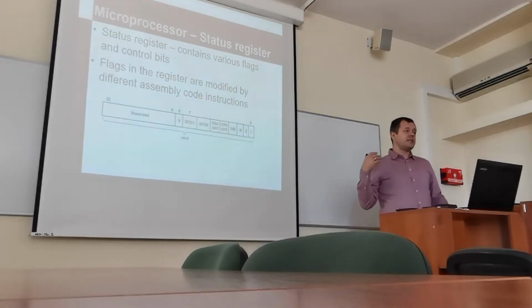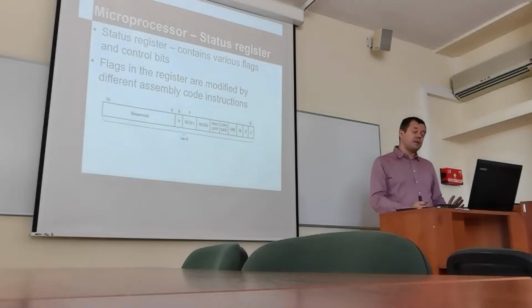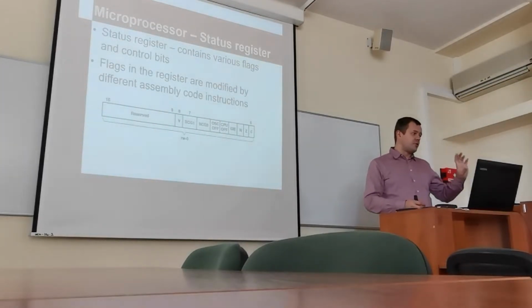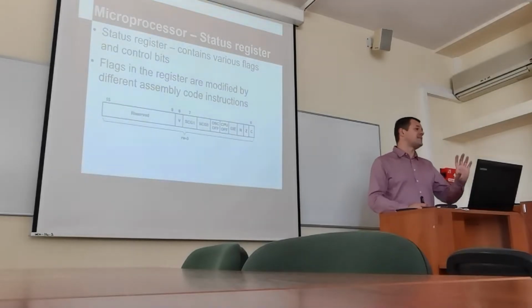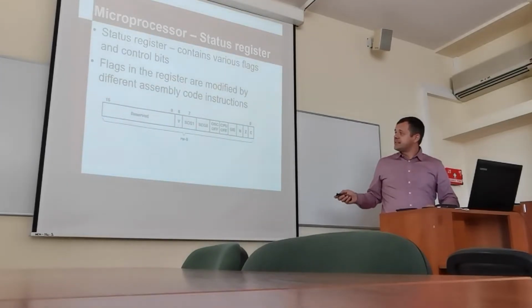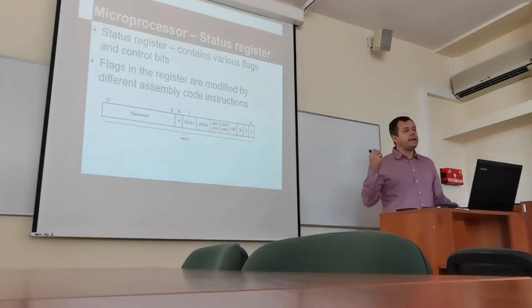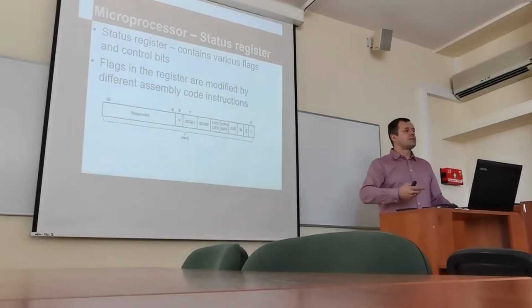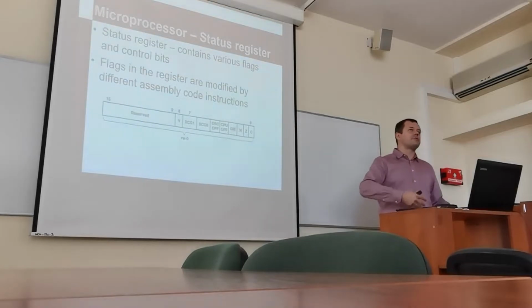But today, status registers in many microcontrollers on the market are used not only to depict the status of the processor itself, but also to depict the status of a microcontroller. Quite often, in case of a microprocessor, we've got some flags about the interrupts, like here in this example we have GIE. IE stands for interrupt enable. So there is always some major interrupt.